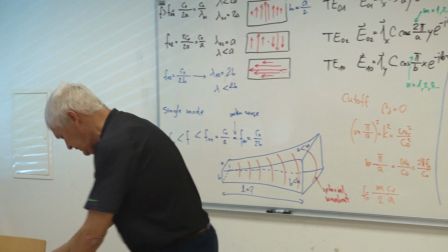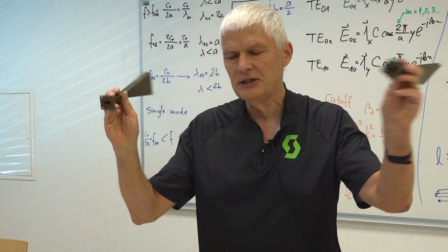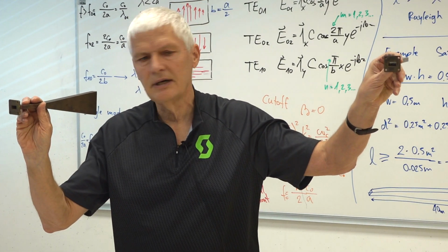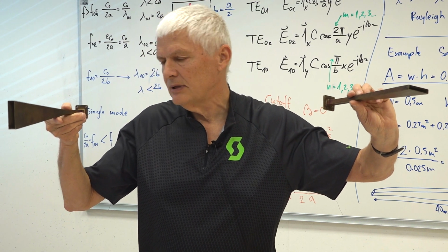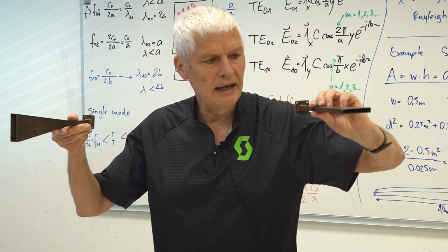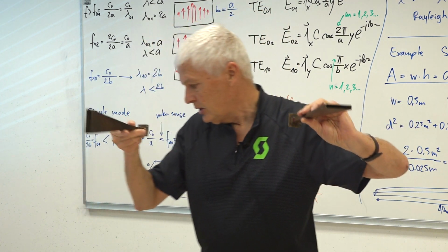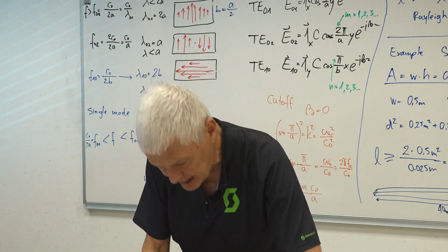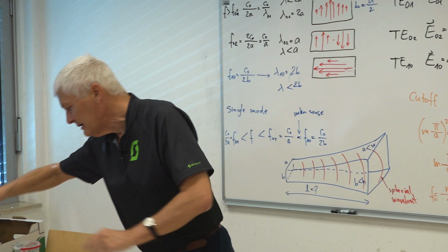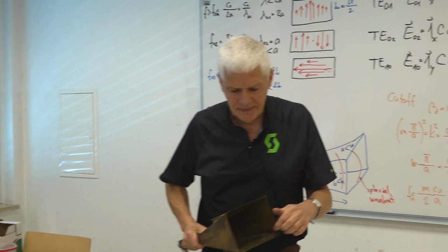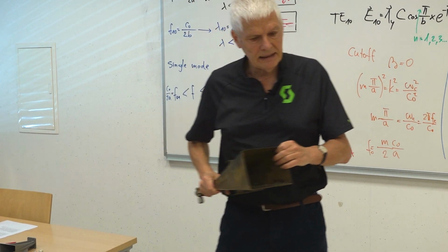I have also for 15 gigahertz the same story. You see this waveguide flange is a little bit smaller because it's for 15 gigahertz. I have the E-plane horn with a narrow beam in the E-plane. I have an H-plane horn with a narrow beam in the H-plane. So I can play with these things by changing the horn. But if I want the maximum number of decibels, then this thing has to be rectangular with a certain ratio of these sides.